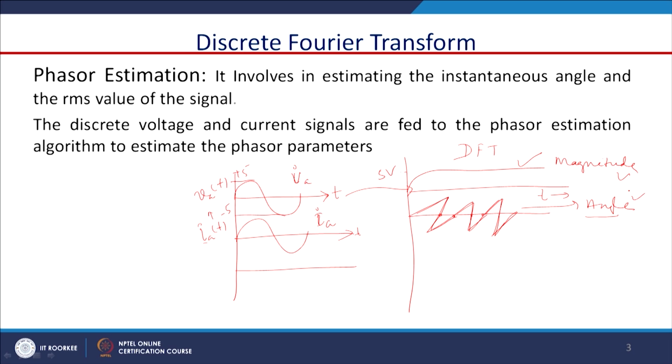So, this magnitude and angle we are interested to extract using this DFT of this particular sinusoidal signal, voltage and current, which are basically the power system. I am just talking in terms of PMU or relaying practice, the relaying field. You will see in the subsequent slides for protection approach, in case of digital relays, the phasors of the voltage and current are very important, because the relays are basically sequence component based relays.